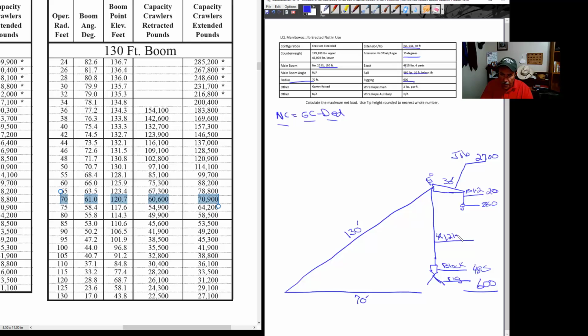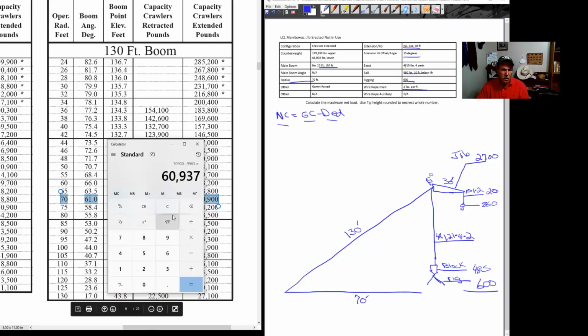We're going to multiply that times 4 because there's 4 parts of line, 4 sections of line. And then we're going to multiply that times 2 pounds per foot, which we get from our data table. When we multiply that out, 121 times 4 times 2 equals 968.